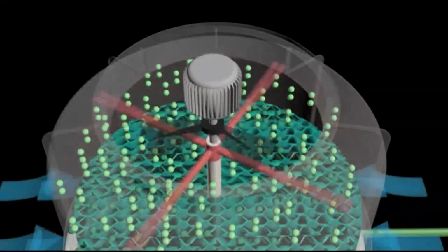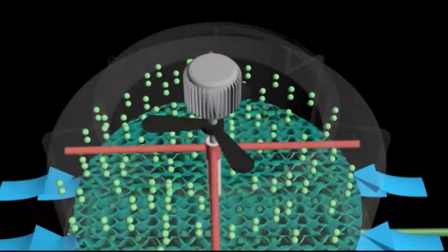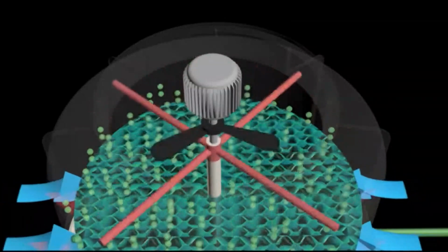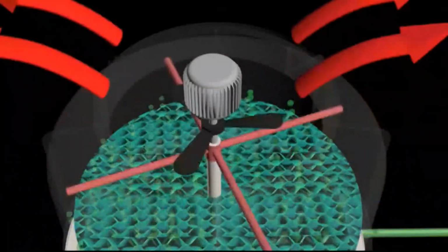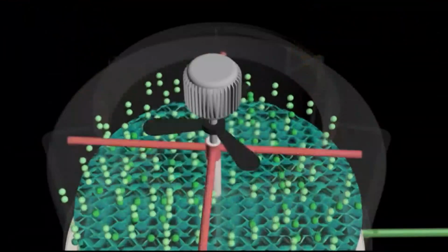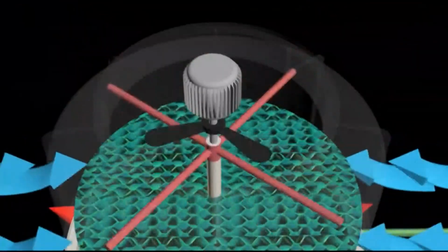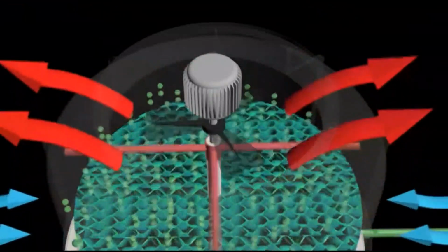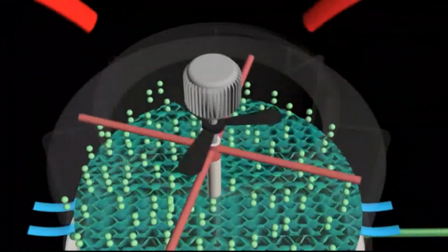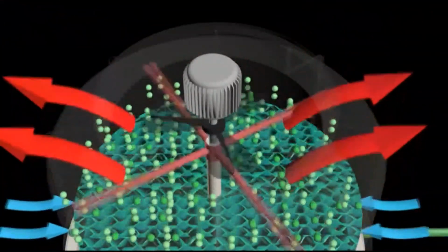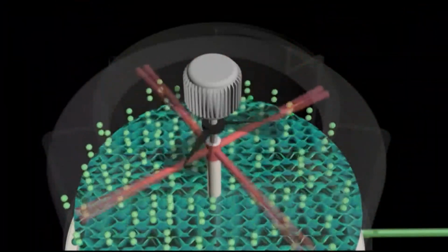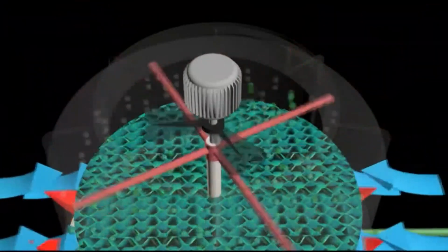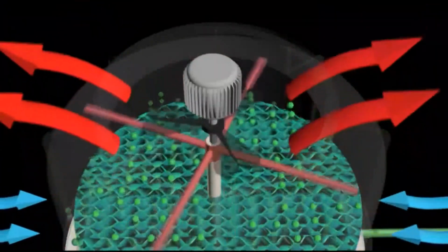Water will gush down through the fins to reduce the speed of water going down. This can delay the time and the heat can be absorbed more effectively by the surrounding air passing through the fins. Air through the fins is forced by a rotating fan on the sprinkler blade rotated by the motor. This fan rotates with its gusts upward. This will cause the air to move from the bottom to the top of the cooling tower, opposite to the flow of the condenser water.